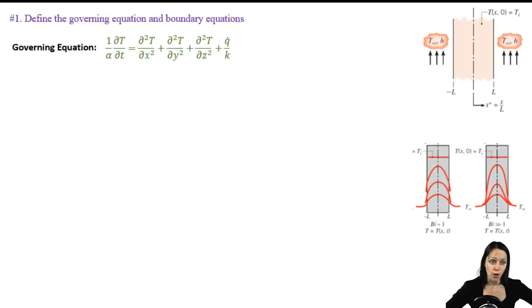So in our case, our governing equation would be the heat conduction equation. It's a plane wall, so we only consider heat transfer in the x direction. There's no heat generation, and because the wall was just exposed to convection, we have a transient problem. It's second order in the x direction and first order with respect to time, so we need two boundary conditions and one initial condition. Our first boundary condition is the symmetry condition.